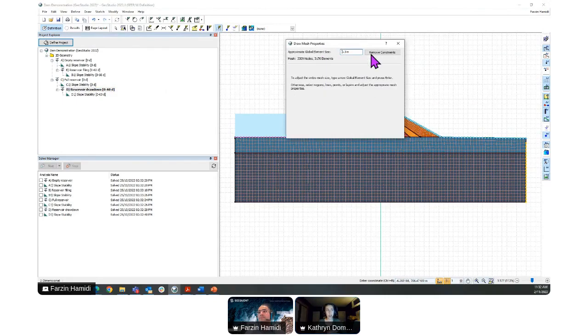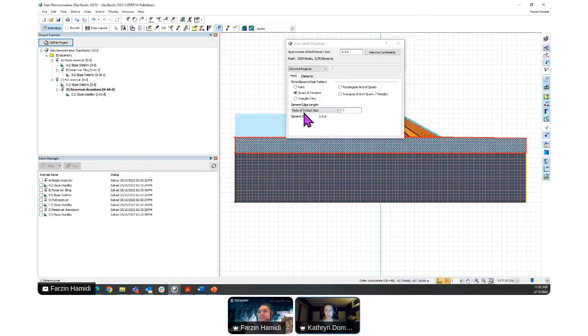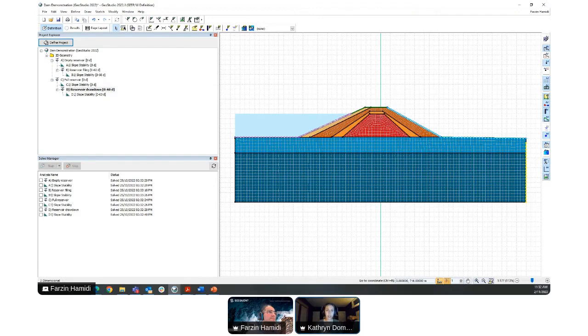You could consider, if the drain is not just in the middle of the domain and completely surrounded by material, if it does extend beyond, for example to the side of the domain, has some sort of outlet, then instead of having a material within the drain region, removing the material and placing a potential seepage face boundary around the perimeter of the material, because that's basically what it will act as in the domain.